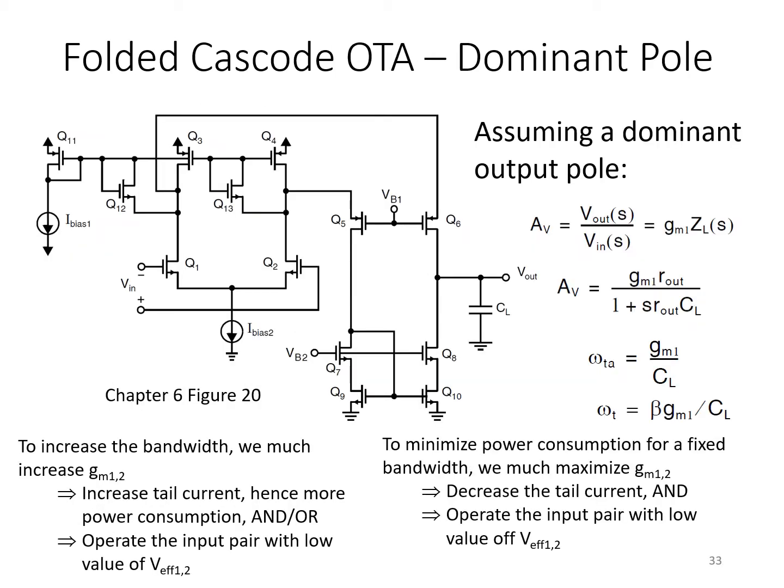Now, clearly this schematic, if we did a rigorous small signal analysis of the whole thing, we would see many poles and even zeros. But fortunately, some simplification is possible. If you take a careful look and go node by node through this circuit, you'll find that the small signal time constants associated with the capacitances to ground at each and every node include a term proportional to 1 over gm, the small signal transconductance of some transistor in the circuit, with the exception of just one node.